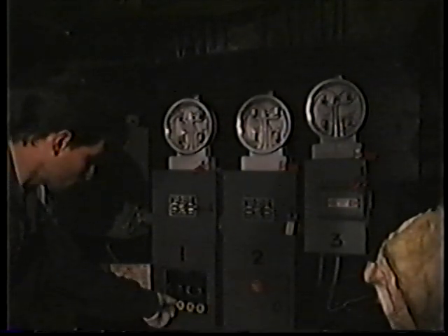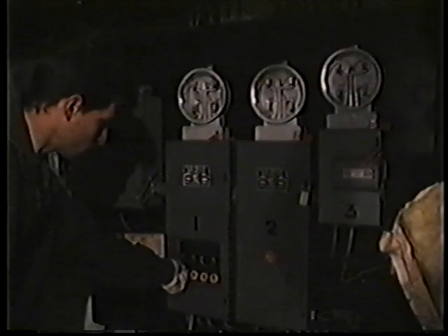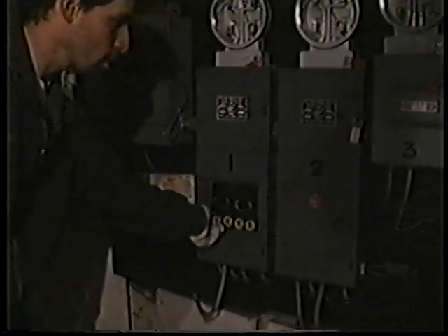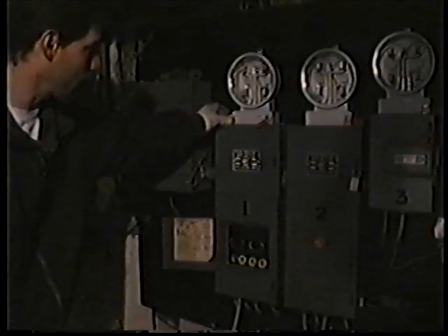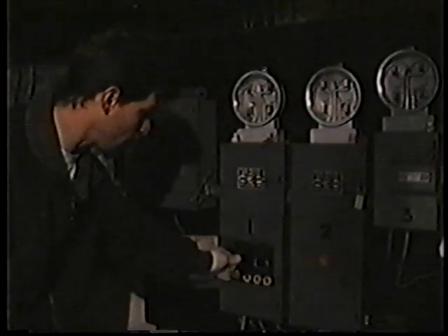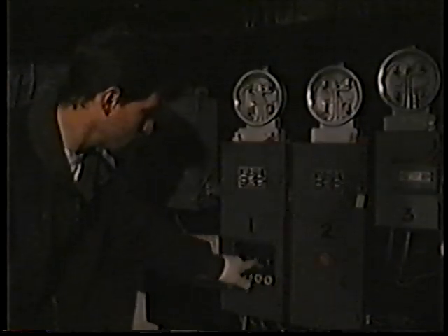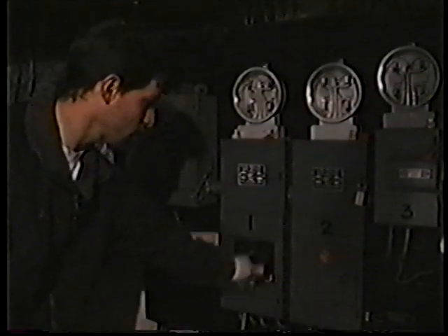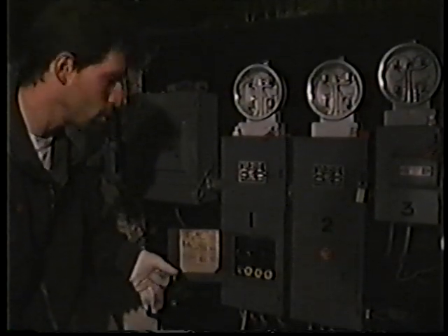This is an old fuse type setup, and a lot of times the biggest problem with these is a wire was only good for 15 amps and everybody seemed to have 30 amp fuses, so they would screw them in and they would fit. And that's where you get a lot of electrical problems and a lot of fires in houses. In these old circuits, they had a pull-out here, which would have shut the whole house down by pulling that one out. Then on this system, they also had another one, which they had just for an electric range or any type of 220 circuitry.